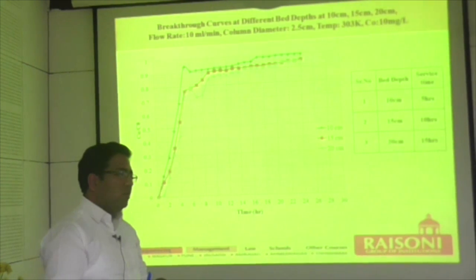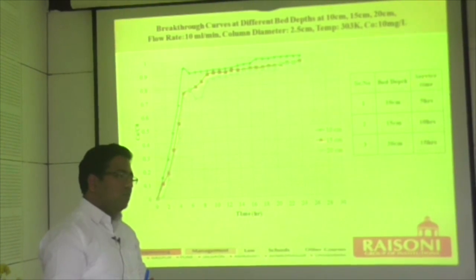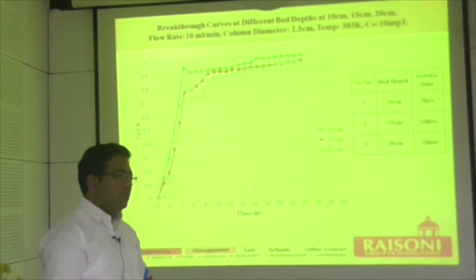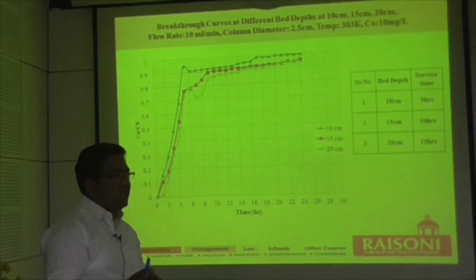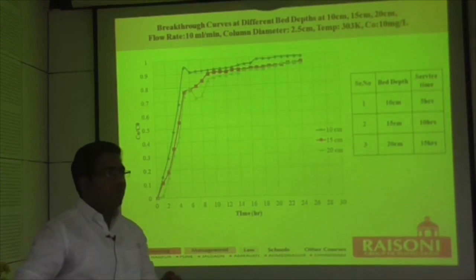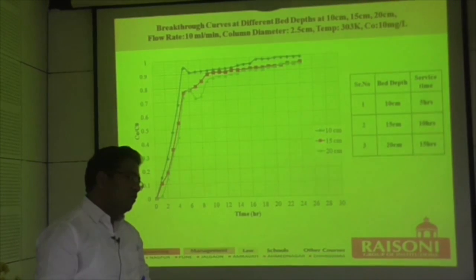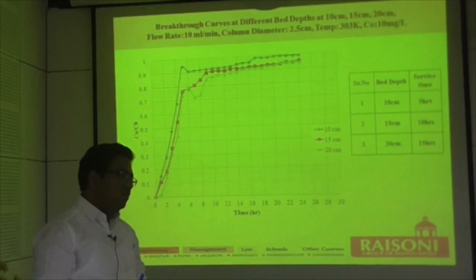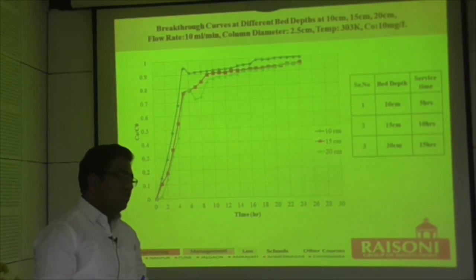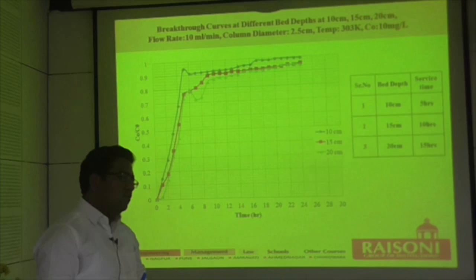What is the particle size of the adsorbent? It is less than 75 micron. Less than 75 microns. So was there any head loss? Yes, sir. It looks like a very fine powder. Initially when I worked, it comes along with the flow. But there is an obstruction below the packing of adsorbent, so that nothing goes down. Was your flow downflow or upflow? Downflow. So you had some barriers at the bottom.